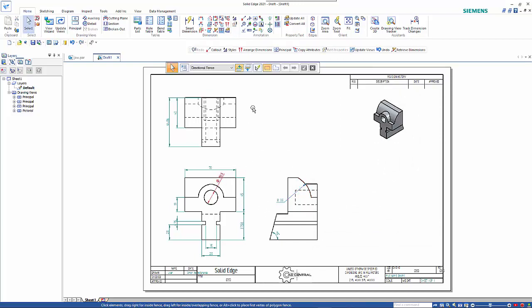I have another one over here, so rather than going through and doing each one individually, we do have an option to copy attributes, and under here we could copy prefixes and suffixes, type, and in this case I'm just going to go style, and if I pick on that one as the reference one, that one as the main one, we can just go through and copy that style through as we need to.